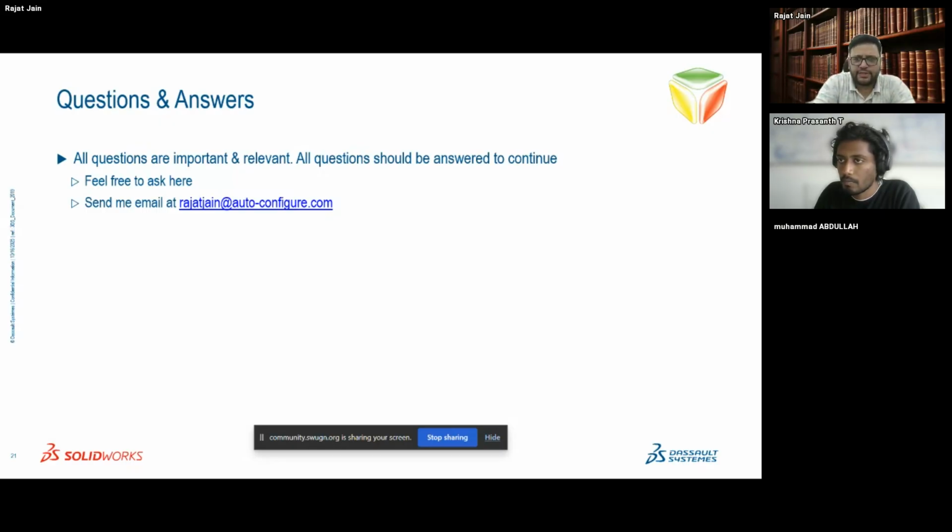You place a sketch on a plane, and there is an origin, and when you pick a point, it has an x and a y coordinate. Now, the recorded macro does not record the point coordinates in the sketch coordinate system, with respect to your sketch origin.